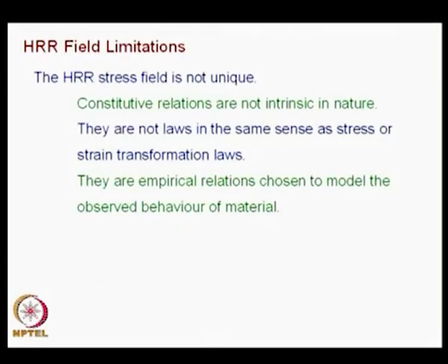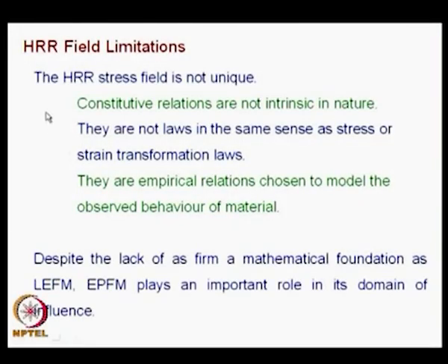Even in CTOD we would come across only empirical relations. So, you have to keep in mind, despite the lack of as firm a mathematical foundation as LEFM, EPFM plays an important role in its domain of influence.